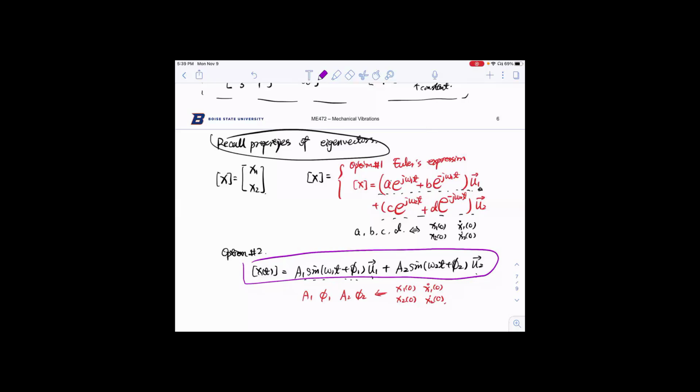If your excitation is in the sweet spot, you would selectively excite the first mode or the second mode. That's actually an important thing for later vibration control. How can we experimentally find out the mode shapes? You have to pick the impact hammer again and hit it in different ways.